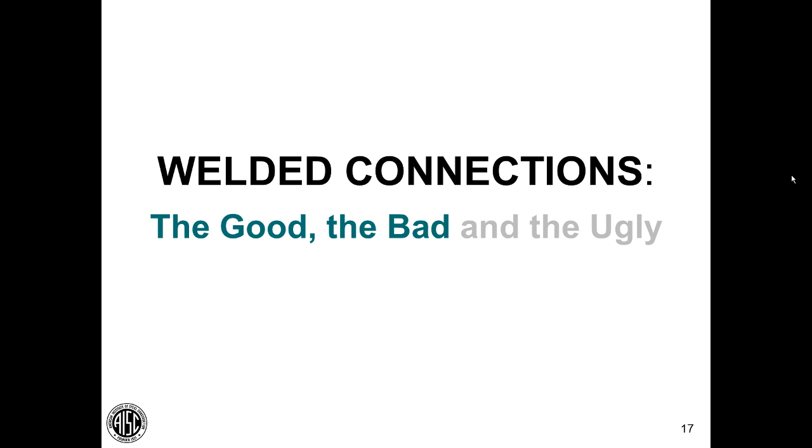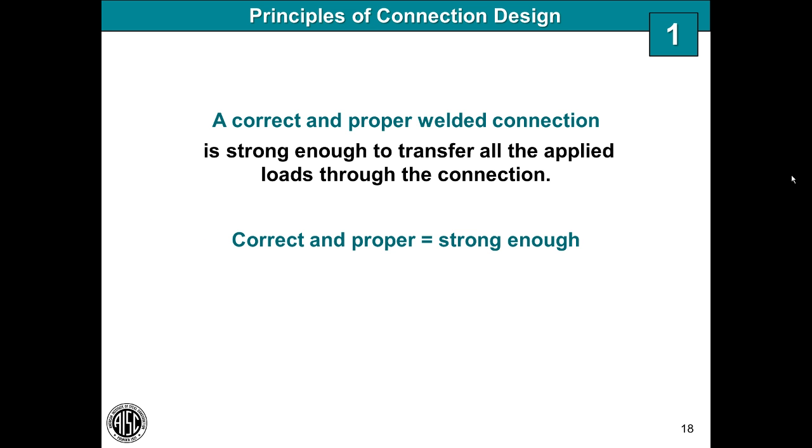The first principle that I want to share with you, a correct and proper welded connection is strong enough to transfer all the applied loads through the connection. In other words, correct and proper means strong enough. Now, there's an immediate corollary to this principle. A good welded connection is not stronger than necessary. In my world, I find more welded connections that are stronger than they need to be as compared to weaker than they need to be.